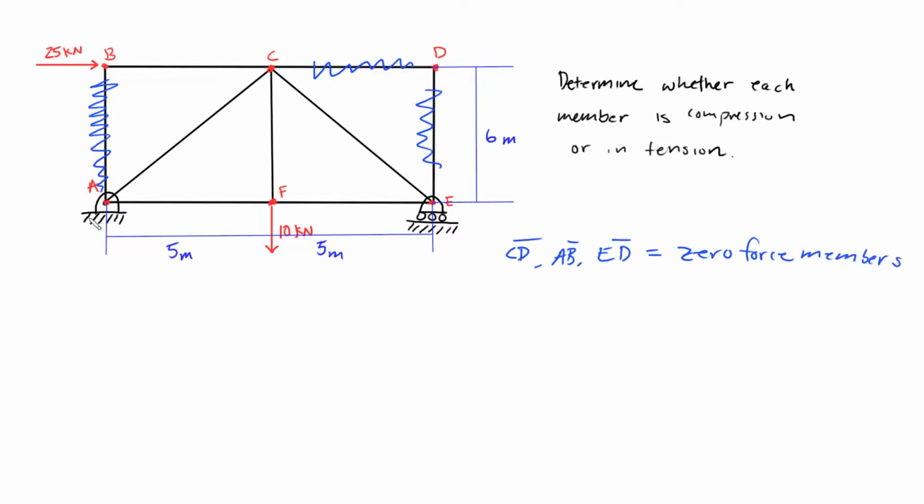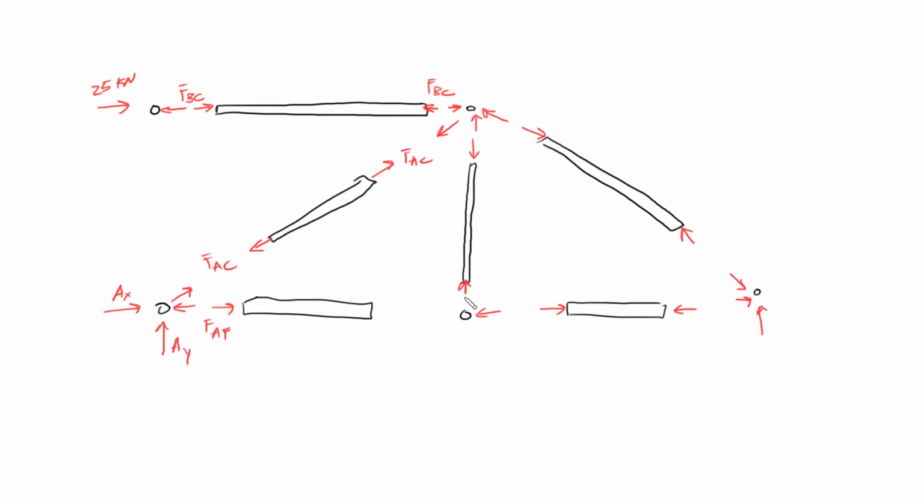So now what I'm going to do is redraw this truss into various components, an exploded diagram, and we'll do some force analysis there. So I'll skip ahead to that. You guys could draw your free body diagram as well. So this is how I drew the free body diagram, the exploded view of this truss, and I basically applied Newton's third law to each of the joints.